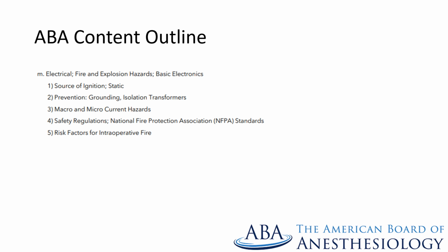These are the key words which we'll be focusing on today. We will discuss sources of ignition, prevention of shock through different types of grounding and isolation transformers, macro and microshock, safety regulations set by the National Fire Protection Association, and risk factors for intraoperative fire.